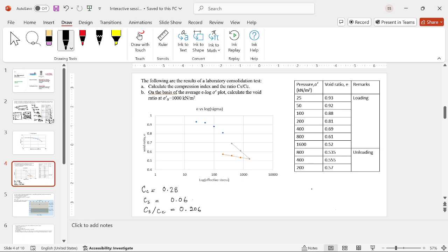So if I place a load of 100 kilonewton on this soil, and before in its lifetime it has only been subjected to 50 kilonewton, then as I am loading it till 50 kilonewton, it will resist. And 50 kilonewton is the pre-consolidation pressure, the maximum pressure that it had endured.